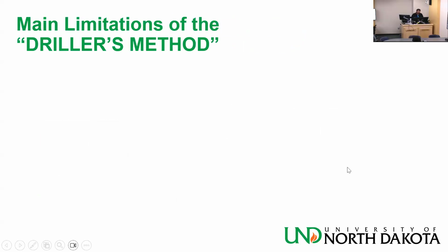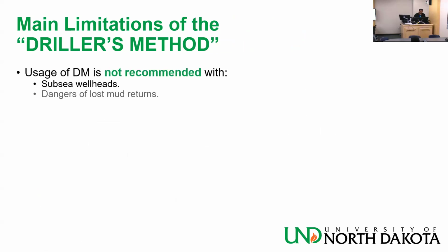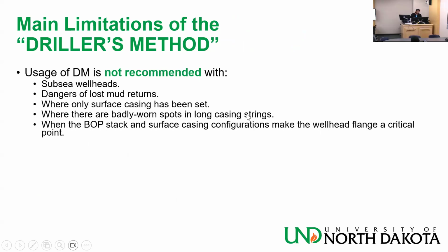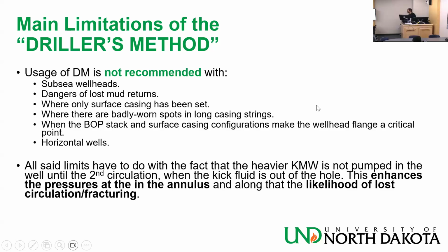Main limitations of the driller's method that I want you to know: it is not recommended with subsea wellheads, dangers of lost mud returns, where only surface casing has been set, where there are badly worn spots in long casing strings, when the BOP stack and surface casing configurations make the wellhead flange a critical point, horizontal wells, etc., etc. Basically, these limitations are all related to the fact that the pressures are going to be higher.